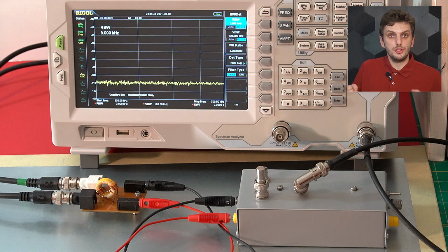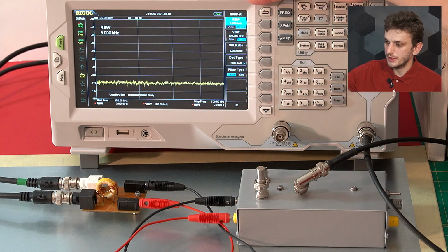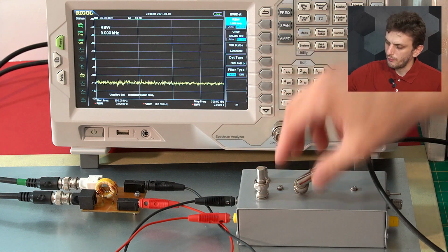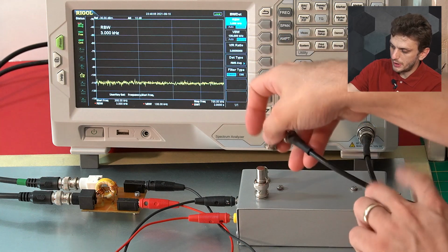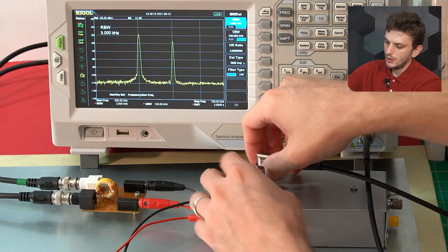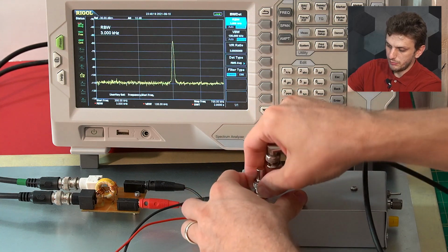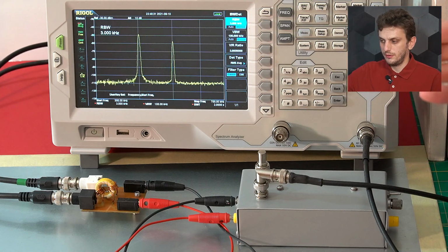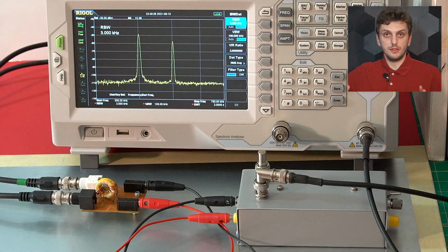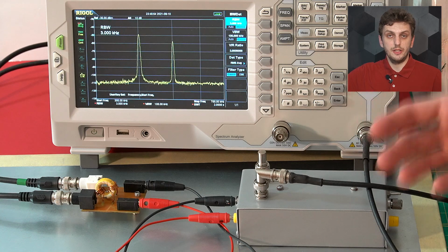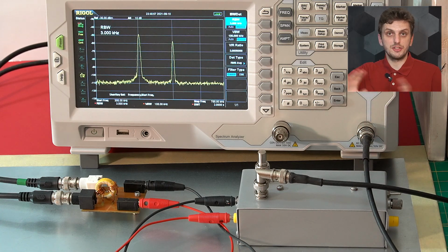First, before trying to separate our noise sources, let's first see how they look on a normal LISN. So for that I prepared the setup right here. I have my spectrum analyzer, I have my noise mixer, which is connected to two channels of a signal generator, and this is connected to an LISN. So if I connect the LISN to the spectrum analyzer, we can see two spikes appearing, one at 400 kHz, one at 500. Now if I swap around the channels of the LISN, so measuring on the other line, we basically see the exact same thing. So just by looking at the noise measurement using the standard LISN, we cannot tell the difference between the two spikes to say which is common mode noise and which is differential mode. And also we can't even tell if we even have both types of noise. We only know that there is noise on the lines.